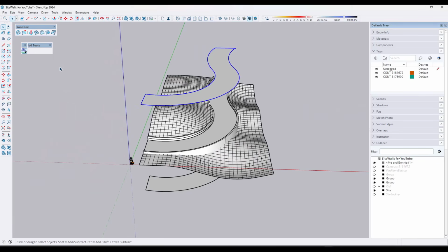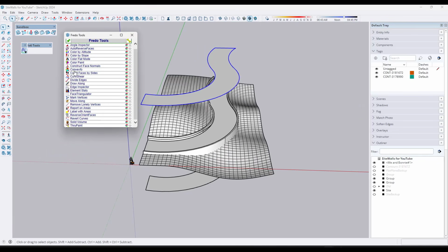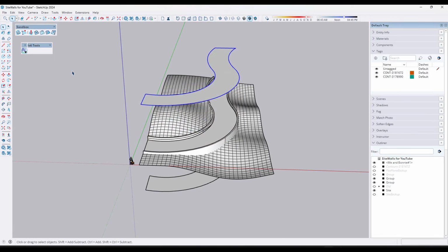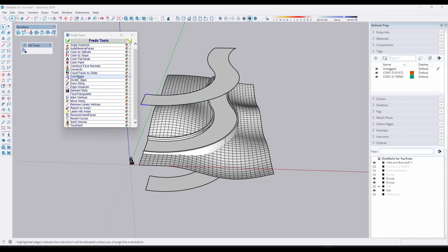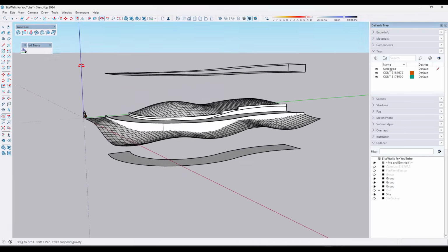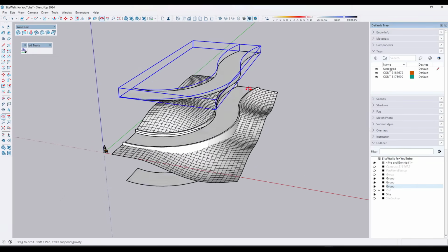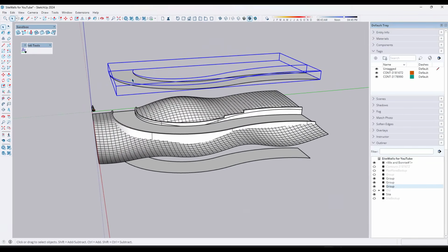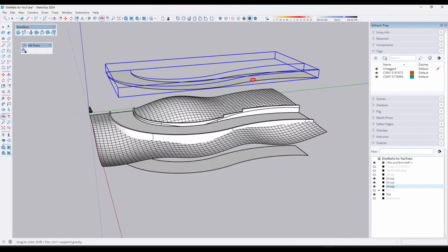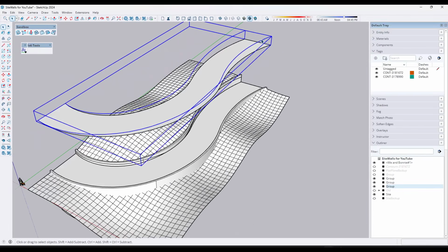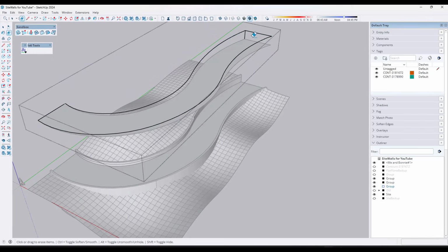But I want it to slope in the other direction. So we're just going to select the option for reverse curve orientation and click on OK. That'll make it move in the other direction. And so now what I've got is a surface in here that actually moves up 7 feet over this duration, like this.